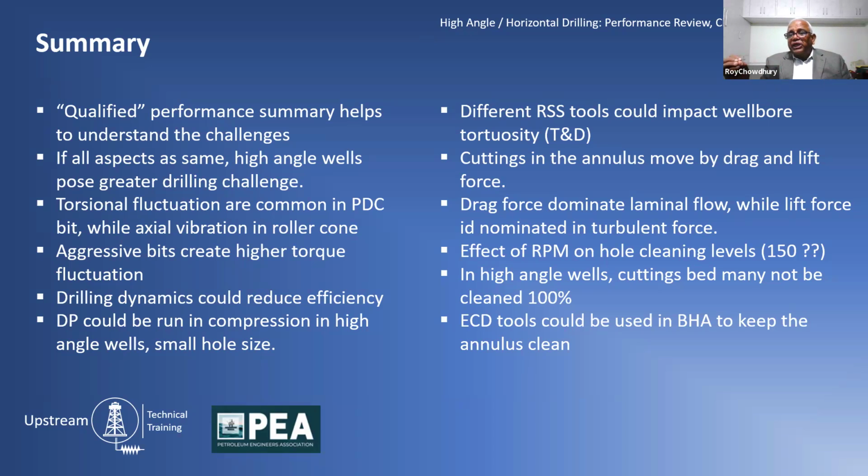Several rotary steerable systems, point-the-bit systems specifically, are known to generate tortuosity if you are drilling too much in one direction with one orientation.